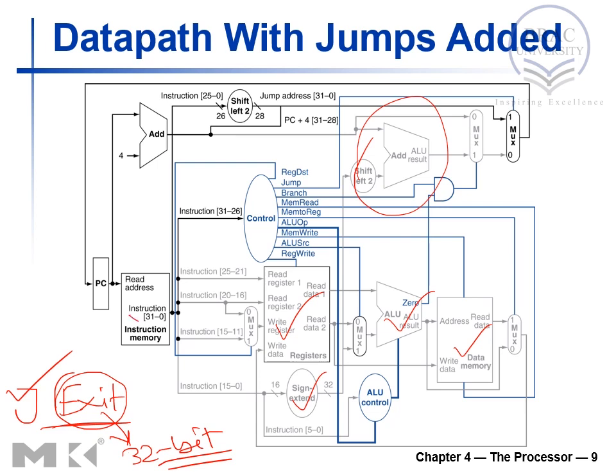We just need instruction memory from where we would fetch this jump instruction. Program counter would give us the memory address of this jump instruction, and we'd fetch the jump instruction from the instruction memory. After fetching, this part works on generating the 32-bit memory address. So this is our instruction, which is 0 to 20. This is our 26 bits, and this is left shift by 2, which gives us 28 bits as it is given here. And then we have this 32-bit address just by concatenating the program counter.